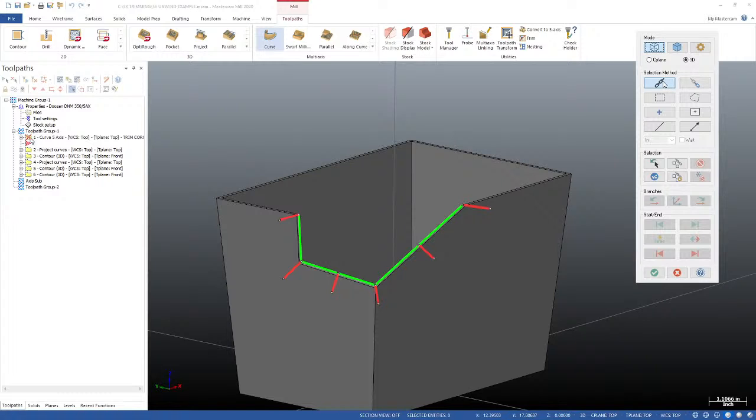Right now it's set to full chain. So if I click on it, it's going to pause at every branch point. I'm actually going to go, well, actually it doesn't matter. I'll go just a partial chain, and I'm going to turn wait on. Wait means I have to choose each branch of the chain in succession.